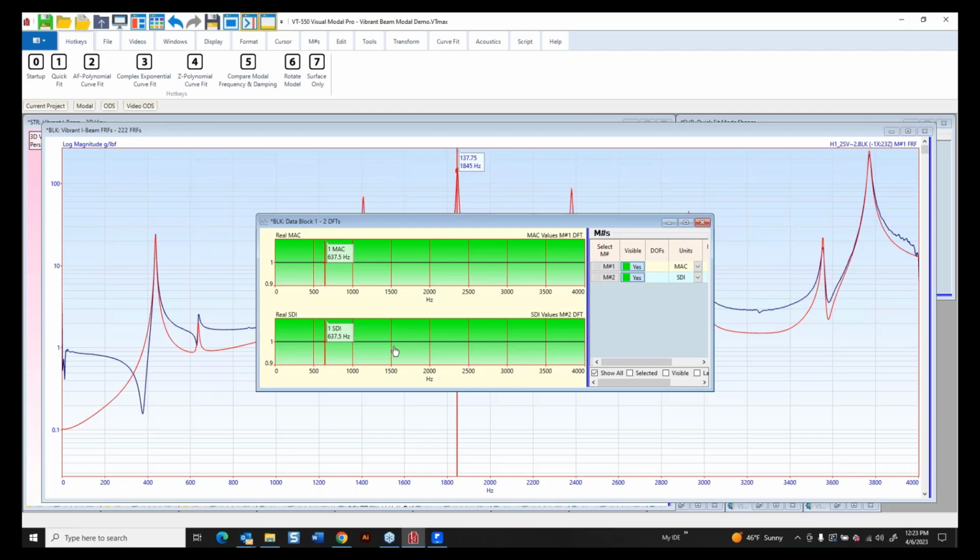In one of my slides, we showed superposition of the resonance curves. That is a linear concept. So does it work in the real world? Yeah, it works with real world data, but there can be cases where the structure is very nonlinear for whatever reason. And so what we're getting if we make FRF measurements and curve fit them and look at mode shapes is a linear approximation of what may be nonlinear or not linear in the real world. Next question.